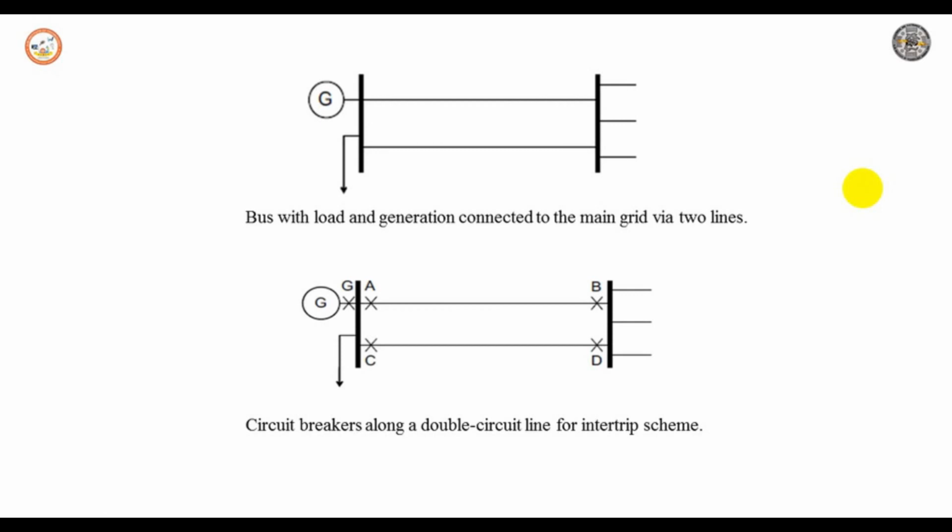When the minimum load is 20 megawatt, up to 140 megawatt, that is 120 plus 20 megawatts of generation, can be connected without overloading the line. However, the N-1 principle is applied to the hosting capacity only for 80 megawatt. That is, we split it up as 60 plus 20.